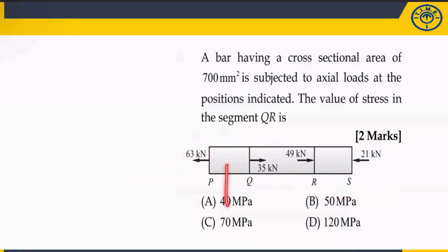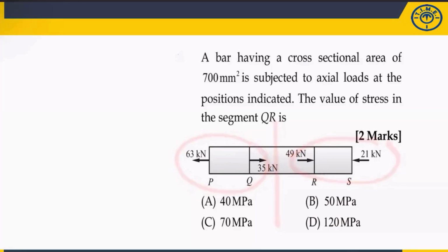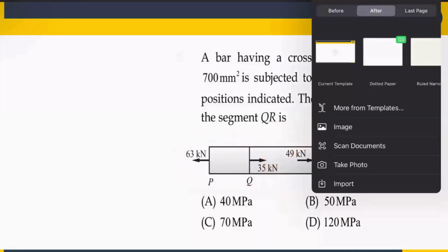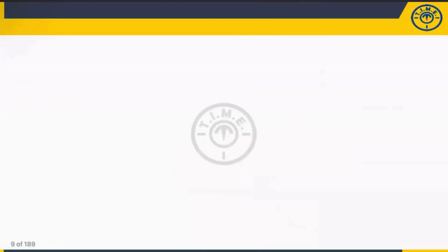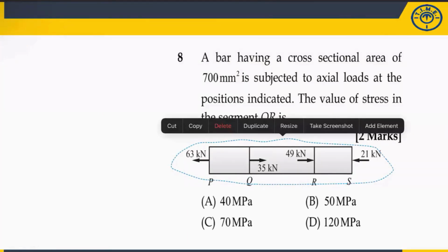Making a free body diagram of these two is very easy. Whatever the force is acting, just apply that. Now the thing is how you will calculate the intermediate force. The same approach: consider a section, take the algebraic sum of either the right hand side or the left hand side. Now I am going to discuss, so you can verify whether you got the correct answer or not. But before that, let me take this figure in the next slide.